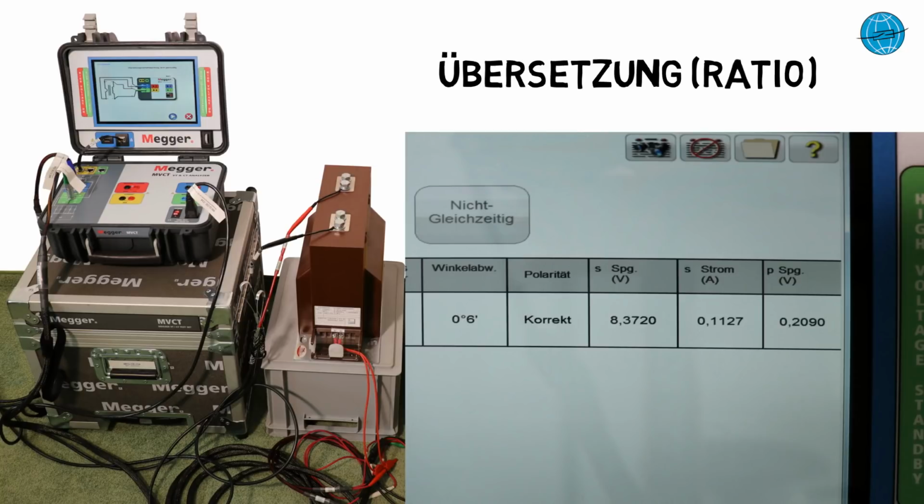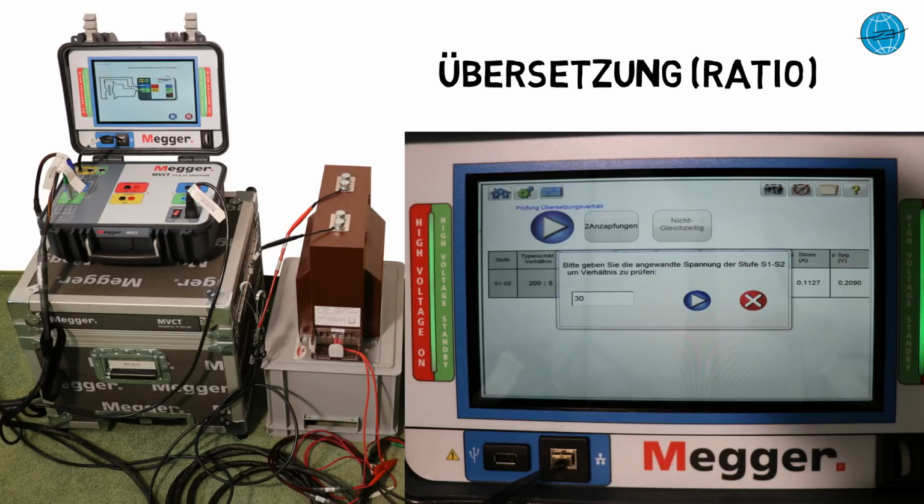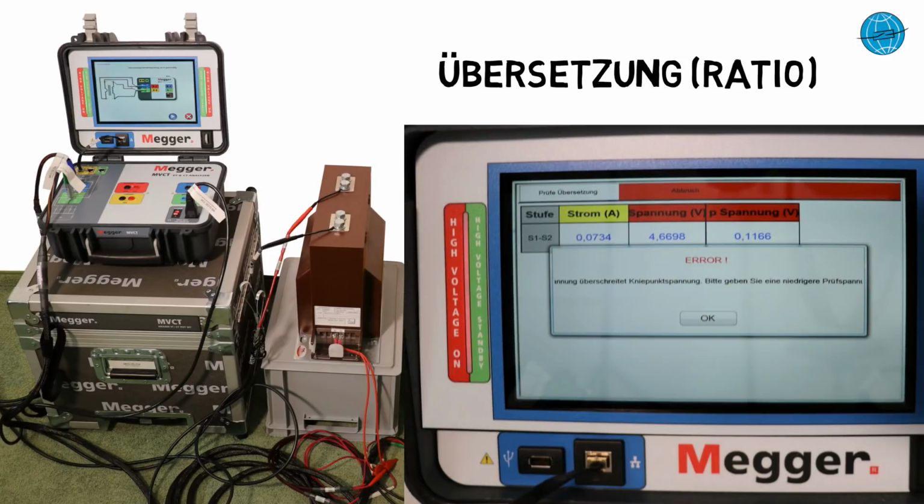But what happens if the user selects a voltage above the knee point as the test voltage? We just try it with 30 volts and run the test. The MVCT starts the measurement and now finds that we are above the knee point, and so no meaningful ratio can be measured. The test is cancelled and we receive the message: test voltage exceeds knee point voltage. Please enter a lower test voltage. An indication of where the knee point voltage is and which test voltage makes sense is not shown.